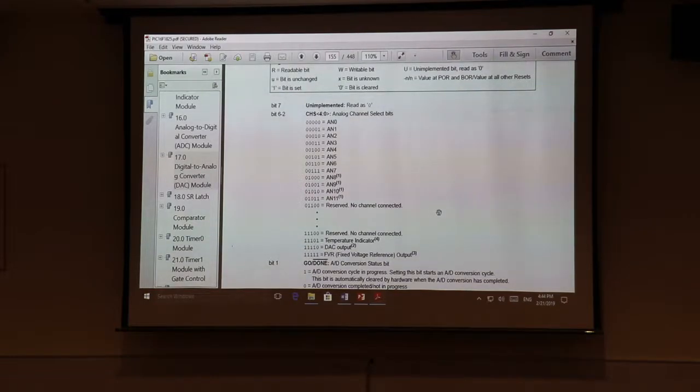So you can select those 3 choices. But if your maximum voltage is, say, 3.3 volts, then the 4.096 selection is not available to you, because that's in excess of the voltage you're providing the chip. So you can't do that one.